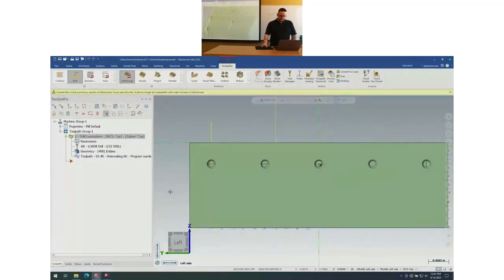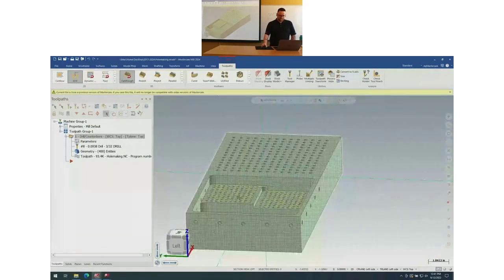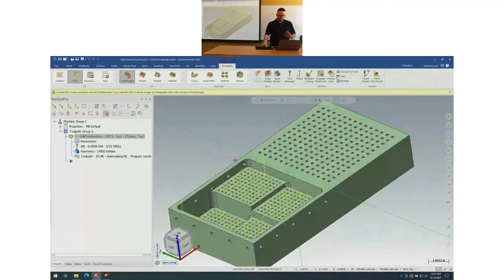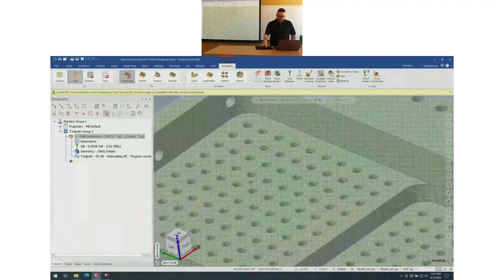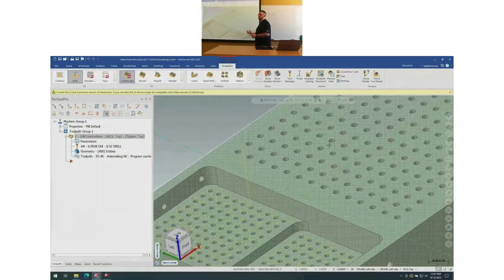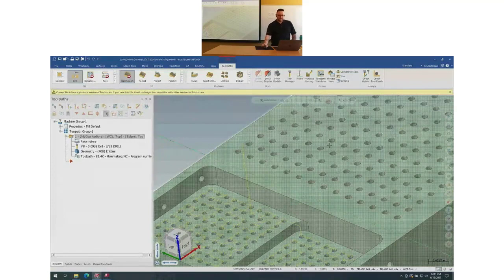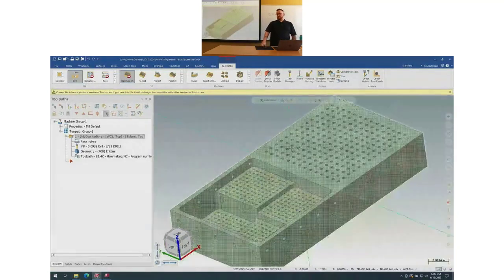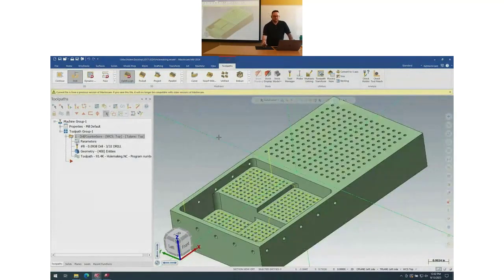The other thing I wanted to mention was the chamfers. So we've got some chamfers on all the holes in here, right? We've got some on these holes and then some on these, and they're different size holes, so the chamfers are also different sizes. So this would be minimum 3 operations to do, right? Small, medium, and then the large ones on the outside. You could actually do this with 1 toolpath using the chamfer mill or the chamfer drill toolpath, which is right here.